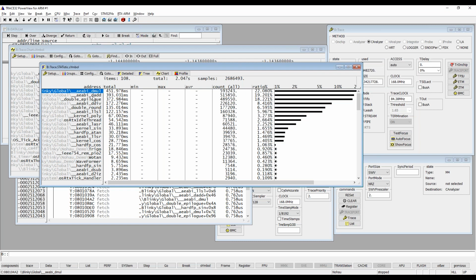Seems to be some float functions and so on in a library, but I don't really know where in my code we are using this library function from. You cannot say that by using the PC sampler, but I will come back to later on how you can do that in another way. But you can get a feeling on where you spend a lot of time and maybe try to optimize that part of your code and so on.